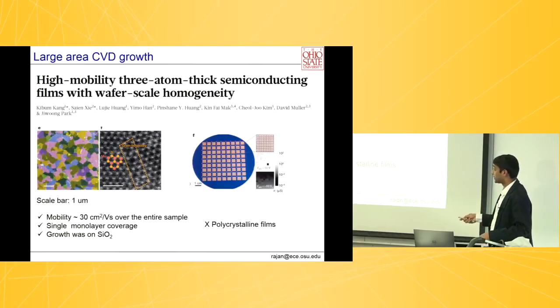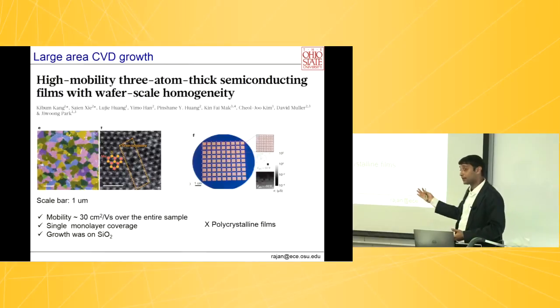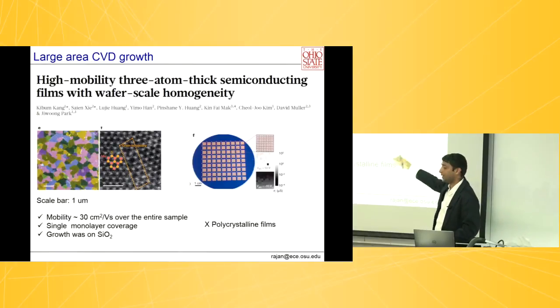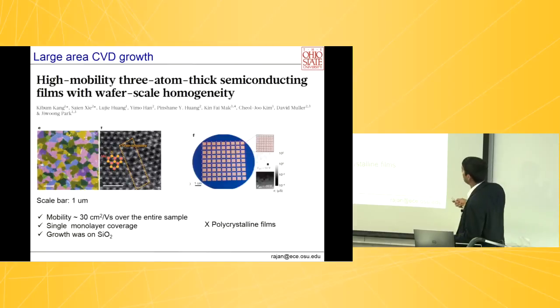Even though they're polycrystalline, they have good mobility, they're optically active. You can probably make different kinds of devices with these. So, like I said, it's not necessary to have crystalline for every application. A lot of TFTs have very low mobility, so they work really well. All the screens that you have, they're all TFTs, flexible displays. So this is an amazing result, I think. And there are other groups also. Again, I don't want to say this is the only one, but this is a very, very exciting result because it's over such a large area.